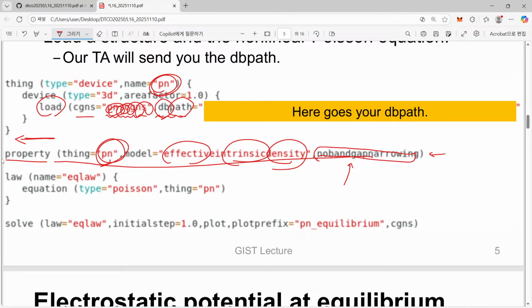If you have a quite clean system, you have the usual EC and EV. However, if you introduce many dopants inside this system, for example, nearby EC, then you have a certain island which is not far away from this conduction band level.